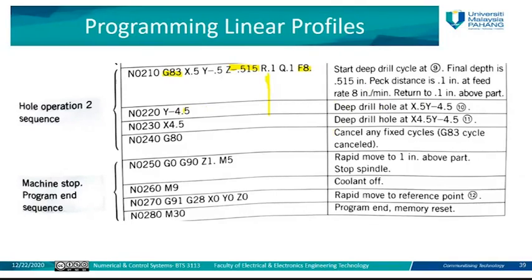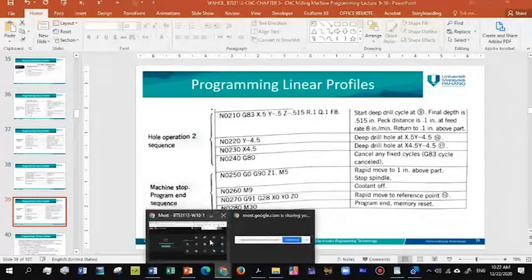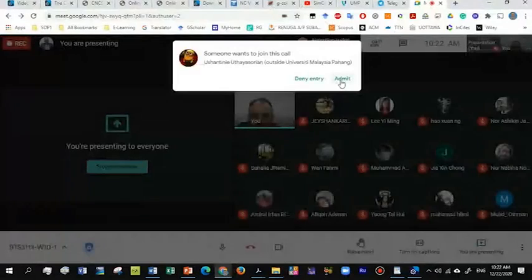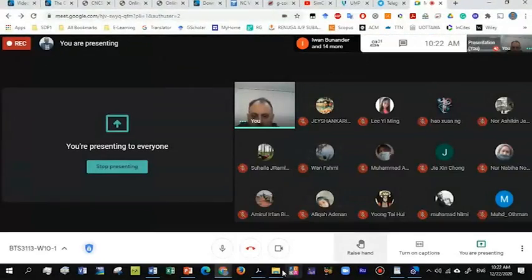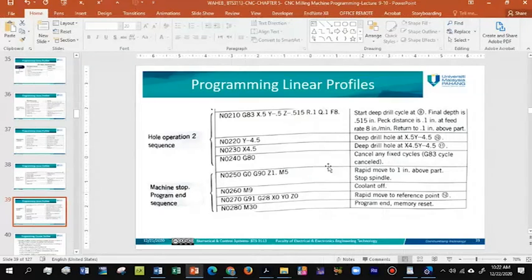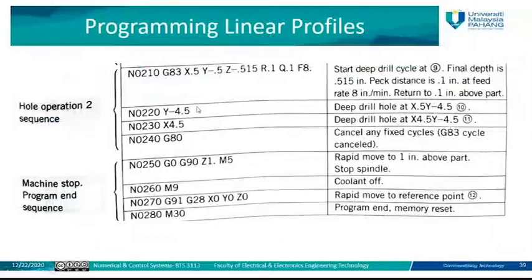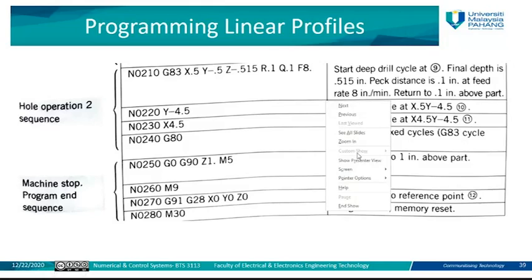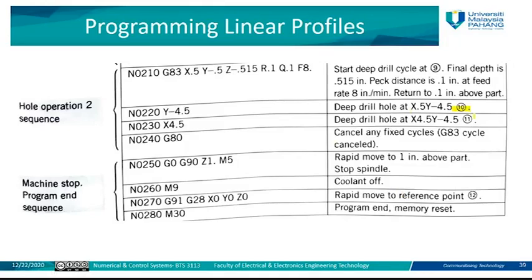So no need to redefine the drill cycle again. We already have it, so just make the drill at node number 9, then define the second position, which is at 10, and at 11, and it will make the drill at point 10 and point 11.